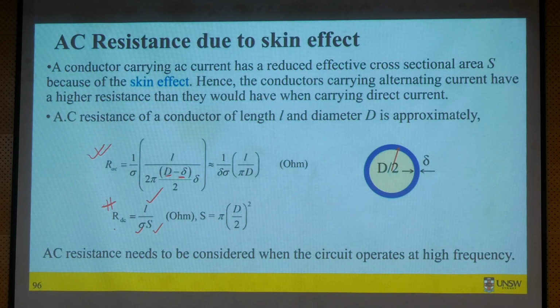Even during your design, especially if you are optimizing efficiency, you need to know whether your motor will see high frequency when it is operating with high switching frequency PWM.